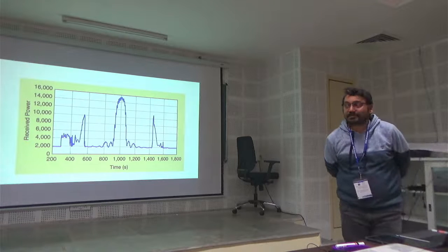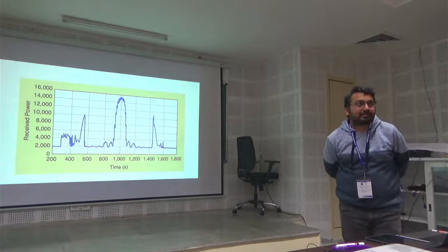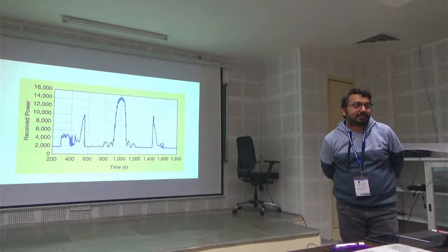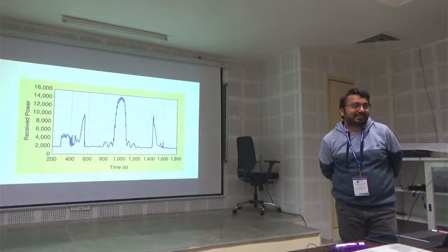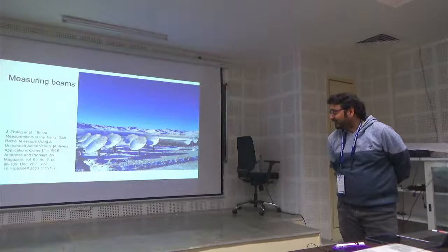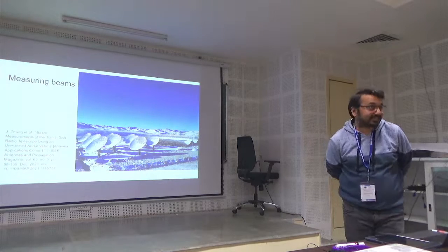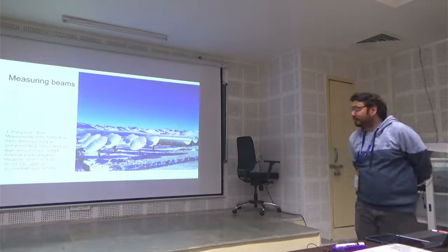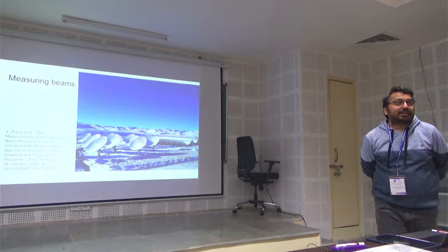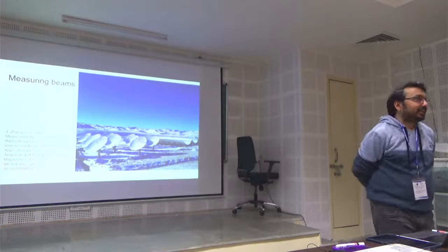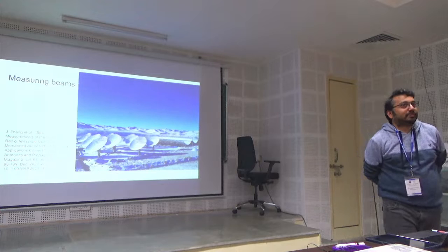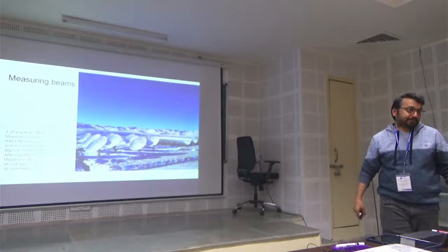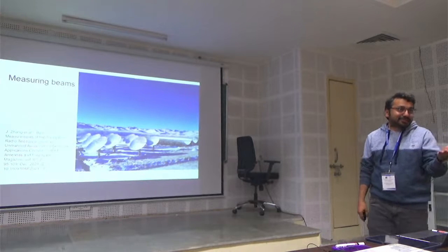We have to be a certain distance far away. Yes. There are so many antennas in the picture that you showed, in the cylinders. Don't they affect it? Great question. Yes, they do. So this has been done for one standalone antenna. The radiation pattern of a standalone antenna can be very different from the radiation pattern of an antenna which is within an array. That is a very active area of research.